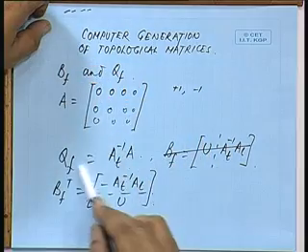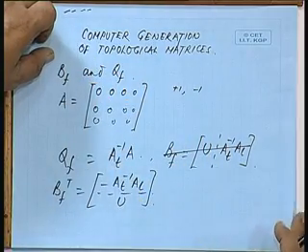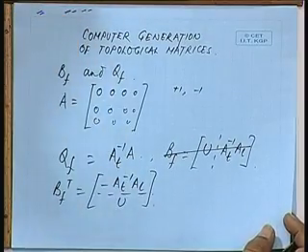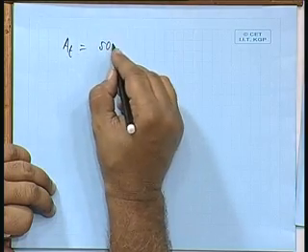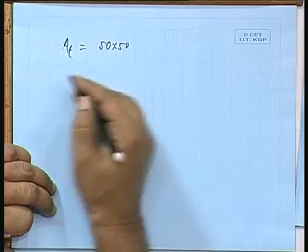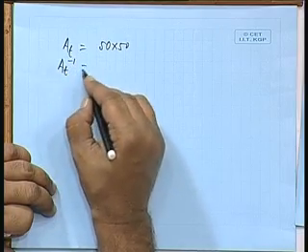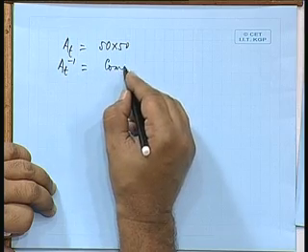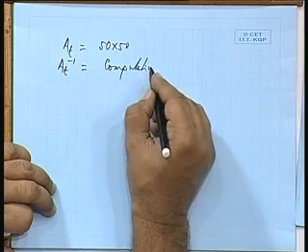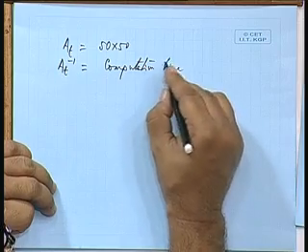So, computation of this will require computation of AT inverse. Now, if you are having say a 50 or 60 node system, then it is not advisable to go for the inversion of such a matrix, because AT will have the dimension 50 by 50 or 60 by 60. You can imagine the number of steps of computation and the time involved will be prohibitive. Computation time is very large.